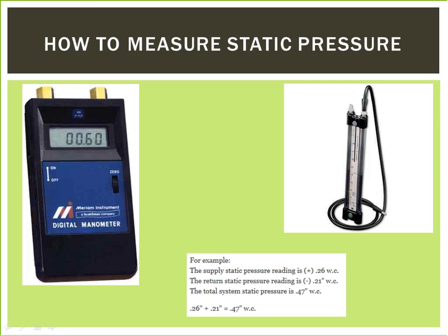Step 4. Read the supply or positive static pressure by inserting the static pressure tip in the test hole into the airstream with the tip facing into the airflow. The magnet on the tip will hold it in place while the value is read and recorded. This measurement is the pressure the fan is seeing on the supply side of the system.